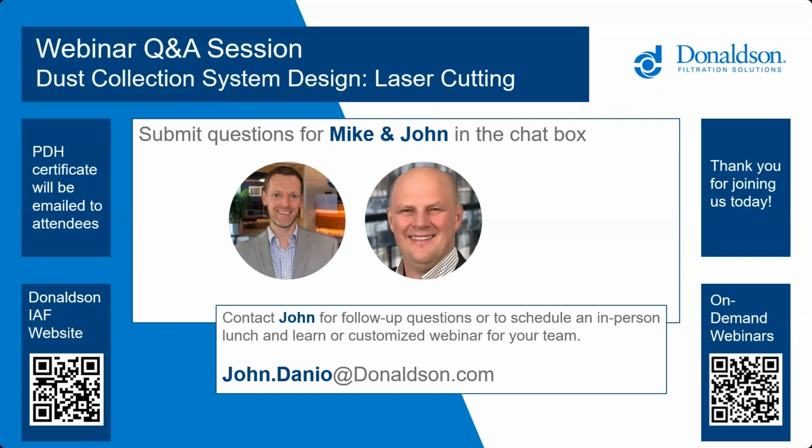Okay, so next question, is condensation a concern with a filter unit located outside? And if so, how is that concern addressed? Yeah, so our dust collectors, depending on the collector itself, are designed to be outdoors. If they are not, there's small modifications we can make to them so they can be outdoors. But yes, condensation would be a concern because cartridge collectors perform their best when the dust is dry and they're in a dry environment.